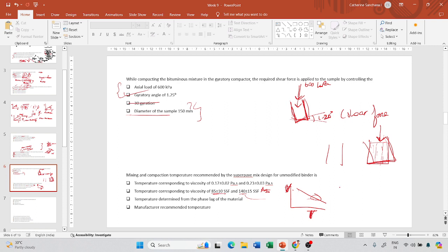So what actually will happen in a rotational viscometer, you will have something called a cup and you will have something called a bob. This cup will be filled with the sample, and you will rotate the bob. The cup will be held stationary, and when you rotate the bob, a shear rate will be induced in the sample, right? And because of this shear rate,